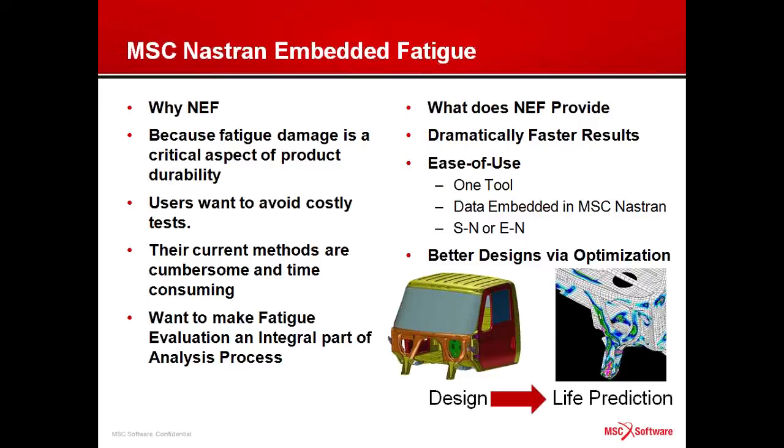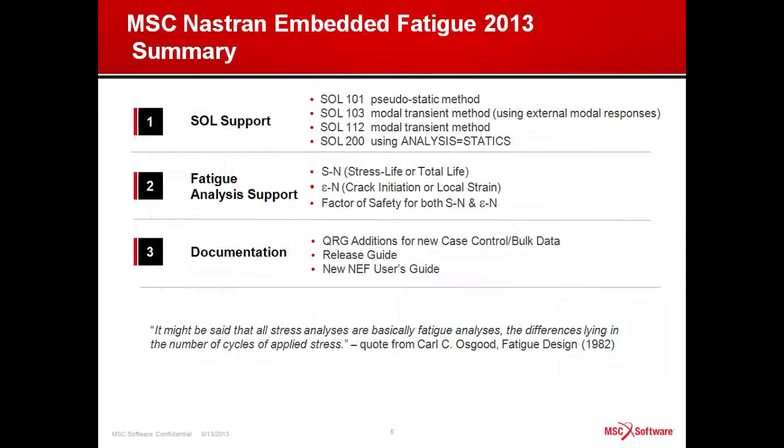So what we want to do is go from the design world to the analysis world to the life prediction in one easy step. In the Nastran 2013 release, this is available for SOL 101, SOL 103, SOL 112, and SOL 200.